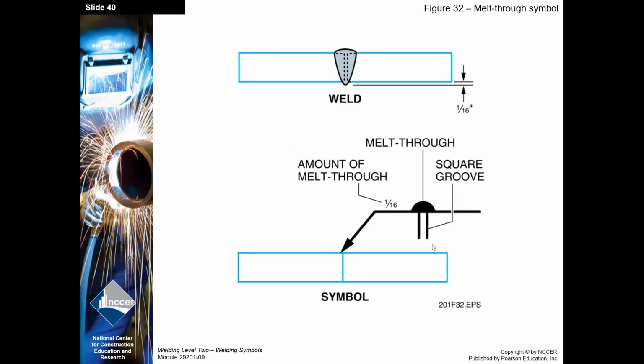It's a square groove. It doesn't tell us the root opening, so slam it shut, I guess, and then punch it through, a melt-through with a 1/16 root reinforcement.